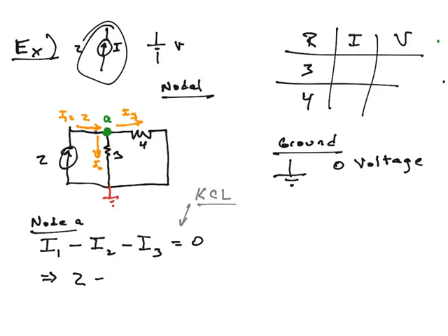So this is when I use V equals IR, Ohm's law. I solve it for I, and I get I as V over R. So everywhere I see an I, I'm going to replace it with V over R. Okay? But what V do I use? Well, this is what we have to see, and I'm going to flip the page really quick to show it.